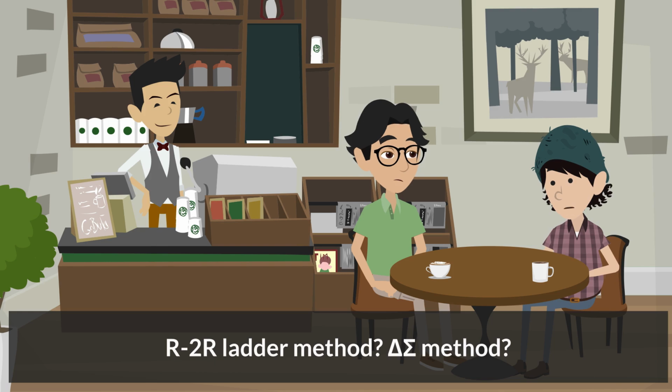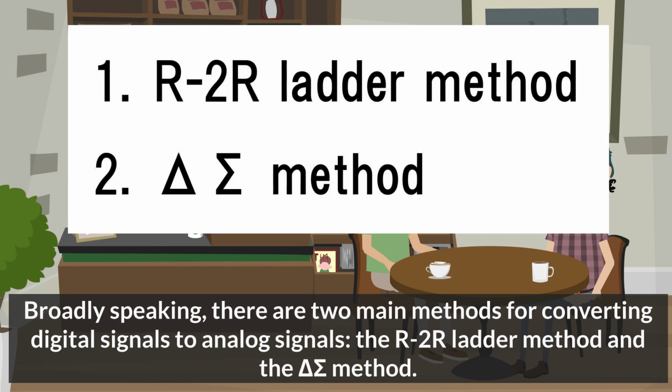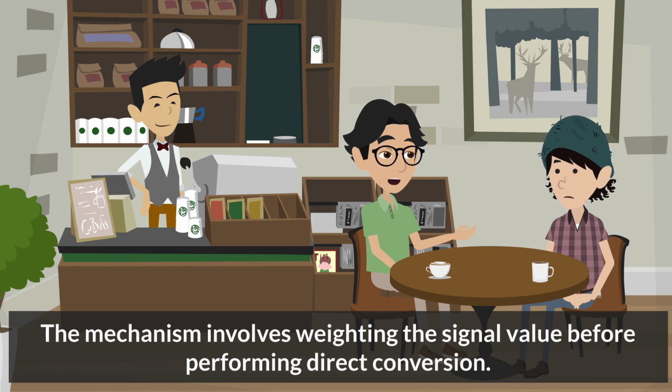R2R or ladder method? Delta sigma method? Trying to explain it in detail just brings up more terms I'd have to explain. Broadly speaking, there are two main methods for converting digital signals to analog signals, the R2R or ladder method and the delta sigma method. First, R2R or ladder method. This is a classic technique that combines two types of resistors, R and 2R, arranged like a ladder. The mechanism involves weighting the signal value before performing direct conversion.